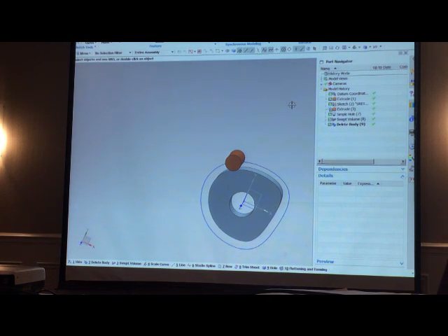So if you're ever in a situation where you've got some spare geometry left over, you only work with bodies, sheet bodies and solid bodies. If you have some spare bodies left over, but you'd like to get rid of them semi-permanently, use this. It's been in there for about 3 or 4 releases now. It's called delete body, which is different than delete.